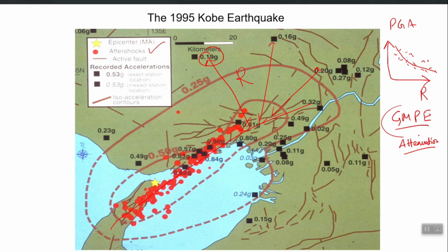So why is it called GMPE? Because it is used to predict the ground shaking for a given distance from the seismic source for other earthquakes. Researchers gather this data for hundreds of recorded earthquakes and then develop equations or models. With a given model available, I can say that I am 50 kilometers away from a particular seismic source.